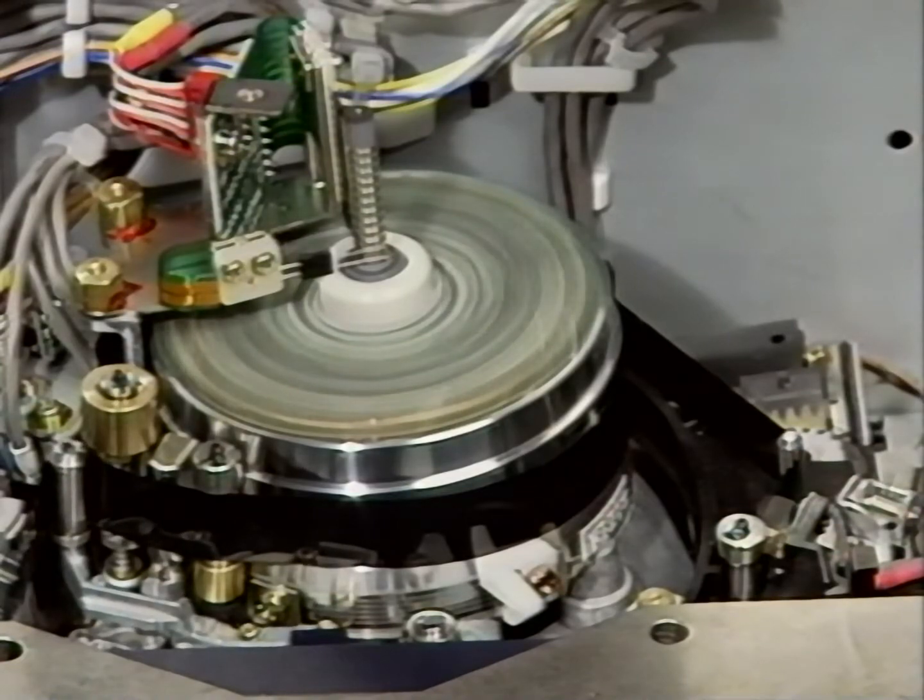As we misadjust RV13 on the SV83 board, we quickly lose tape stability. Note tape slack at the entrance side and the motion of the tape drawer arm attempting to compensate for tape slack.